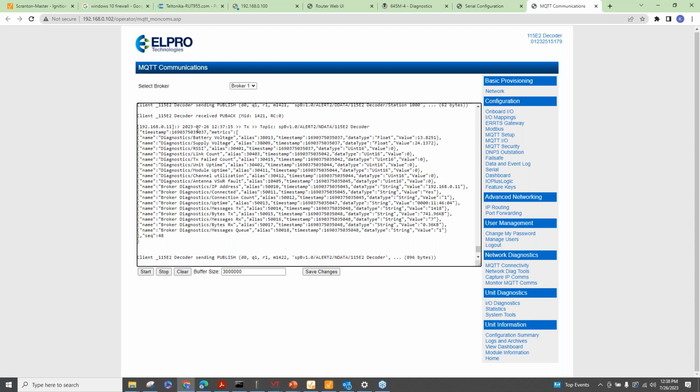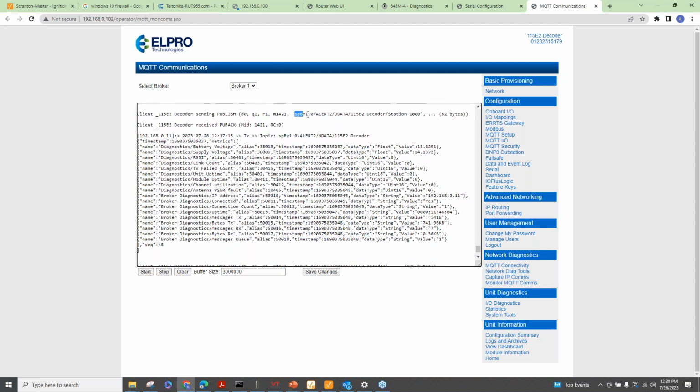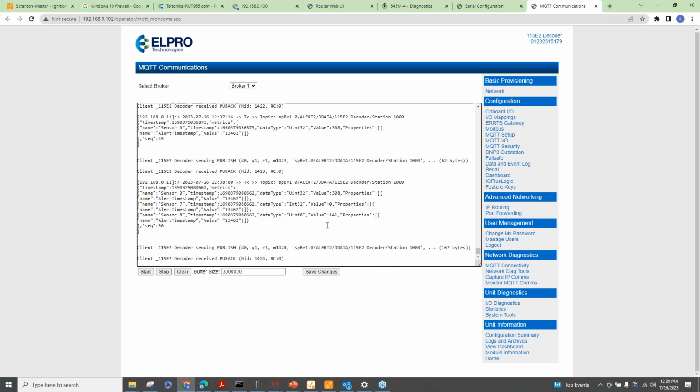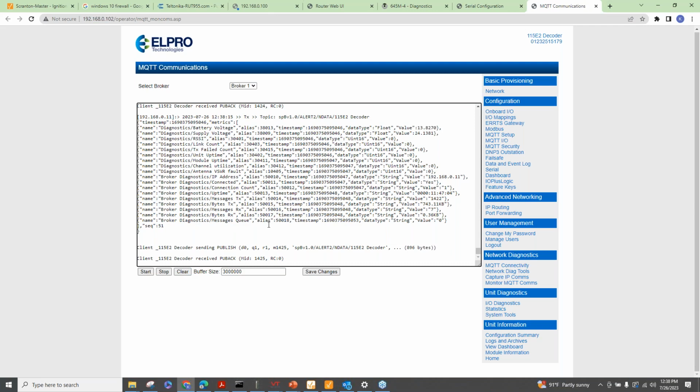So notice how the structure is. It has this structure right here, which is different than if you would have done it with just plain MQTT. So this is the Sparkplug B standard right here. And because you're using Sparkplug B, you have that advantage, but it also compresses the data 3 times, and you can save data rate on your cellular connection, because it's a much more efficient network compared to, for example, Modbus.